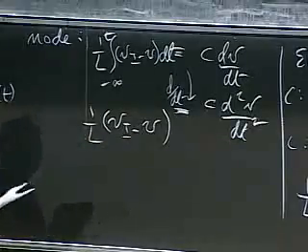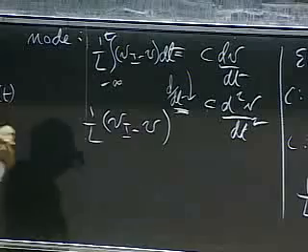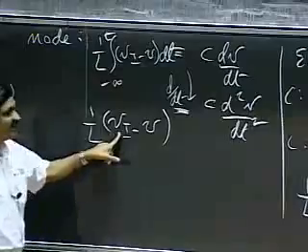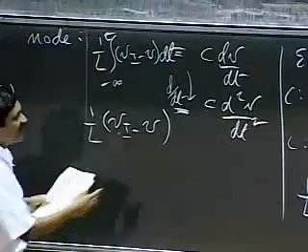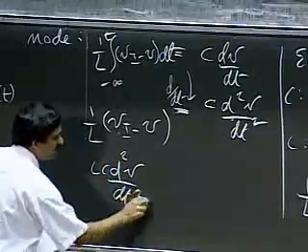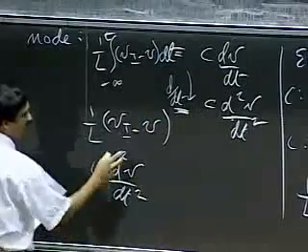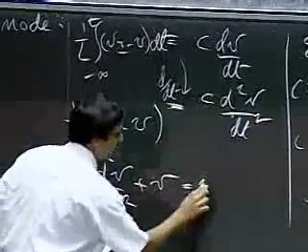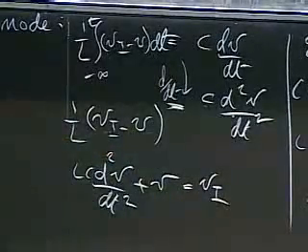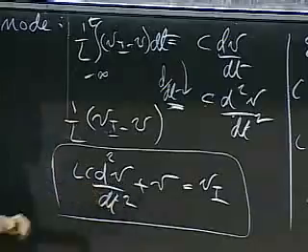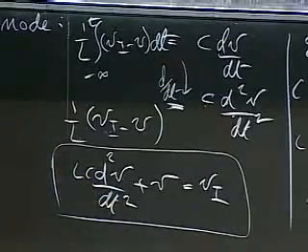I'm sorry, let me leave this here. Bring the minus V to this side so it becomes a plus, and leave VI on this side. Okay, so I end up getting LC d squared V by dt squared, I bring L up here, and then I take V to the other side, plus V, and leave VI here. So I get VI. This is the second-order differential equation that governs the characteristics of the voltage V.